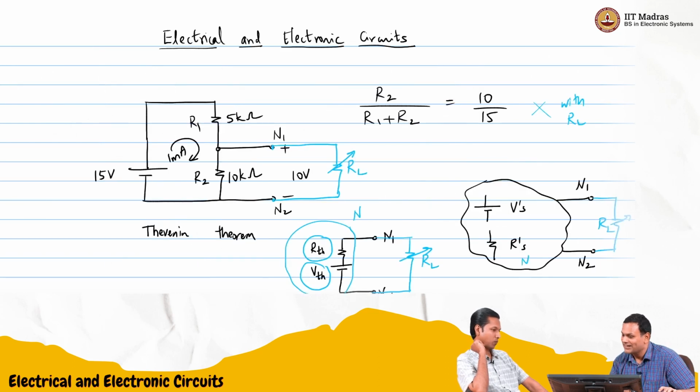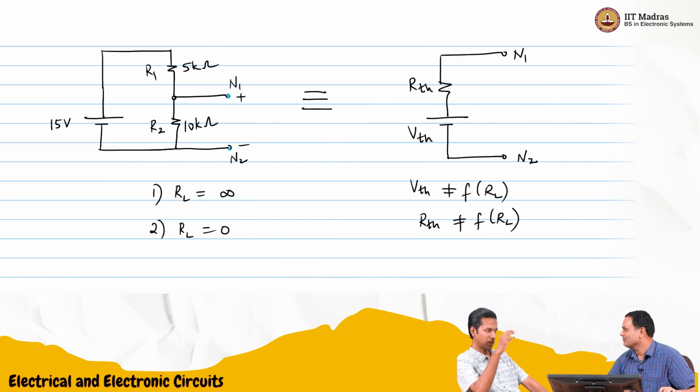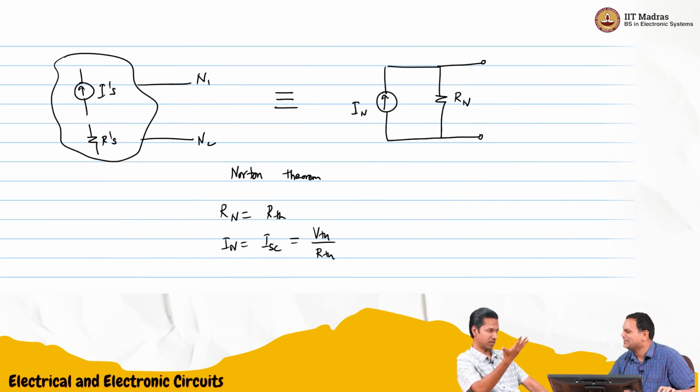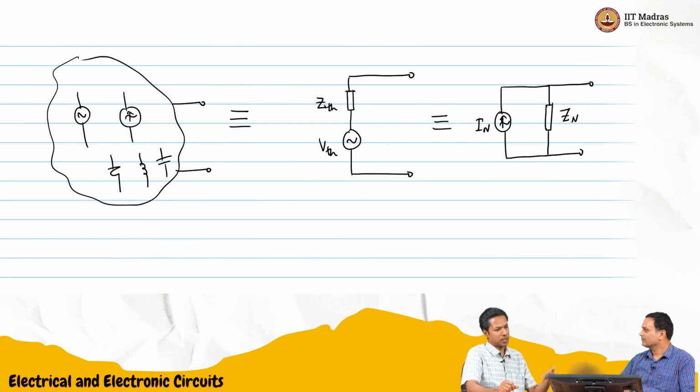When we actually connect a load, it is not giving you the actual voltage. Most likely there must be some internal resistance. Sometimes when we use this 1.5 volt DC battery and measure the open circuit voltage, there is 1.5 volts. If I connect a bulb and then measure, it's slightly lower than 1.5. It is giving less light than what you expected.